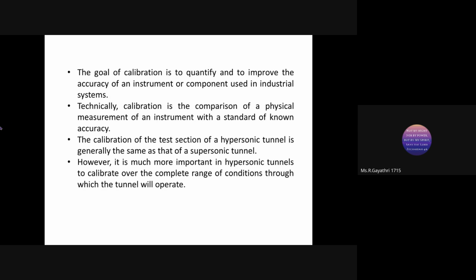The calibration of the test section of a hypersonic tunnel is generally the same as that of a supersonic tunnel. What we do in supersonic can be followed in hypersonic also. In supersonic we can check the pressure if a manometer or other devices are used. Similarly, here also we can use output verification with standard data.